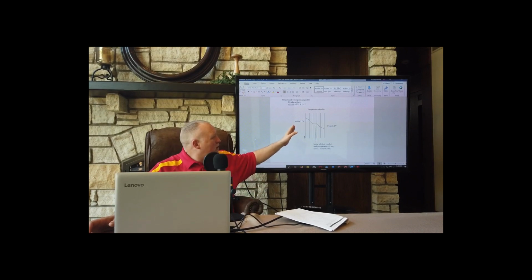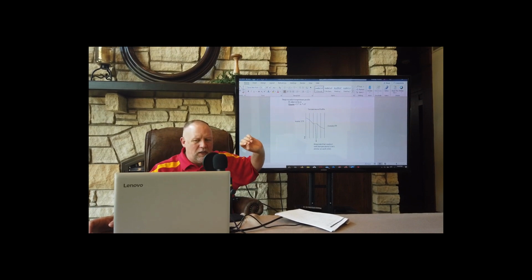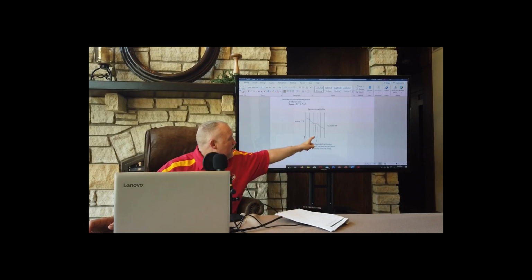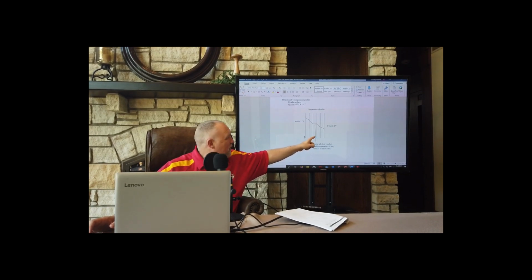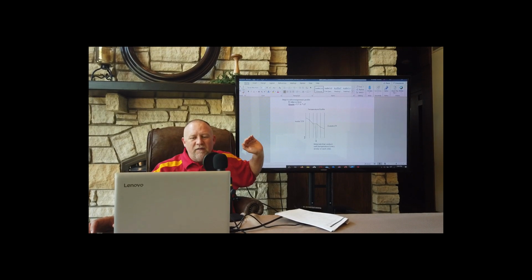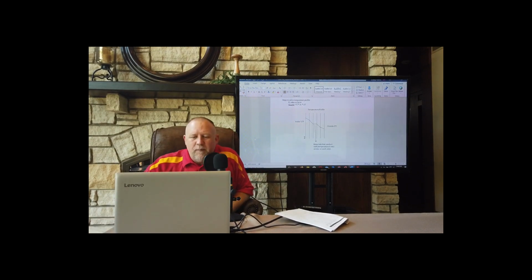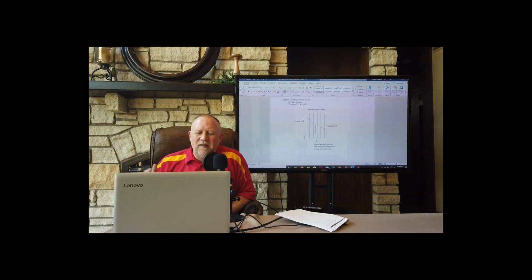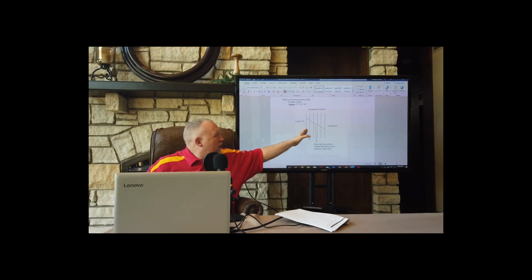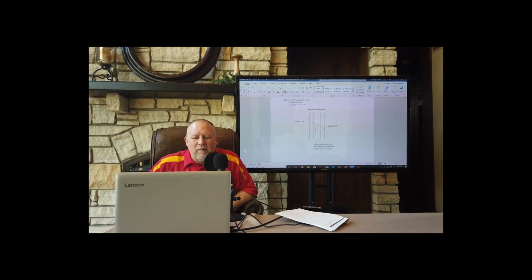The temperature is going to change in proportion to the R value of the item it's going through. For example, something like steel, like let's say that those were steel studs here, has a very, very low R value. There's almost no temperature difference across that. However, something like this, with a very steep profile, that's an insulation or something that has an insulating value, and you're going to have a much greater temperature change as you go from inside to outside. The slope of this curve is proportional to the R value of the item that it's going through.